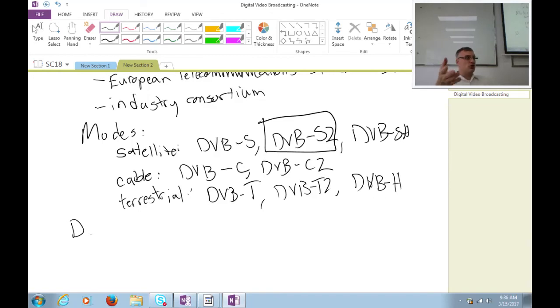Distance, that's right, which of course translates into path loss. So we would expect the most path loss on average in our satellite links. So you'll see that the modulation is kind of tailored for that. By and large, satellite uses lower order modulation, small constellations, QPSK, APSK, a couple higher order modes in case you do have some extra link margin. But Muliang is right, the extra distance means that by and large we're not using the higher order constellations that cable, for example, would use.